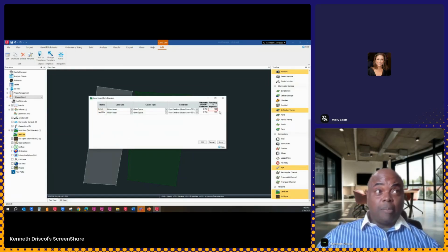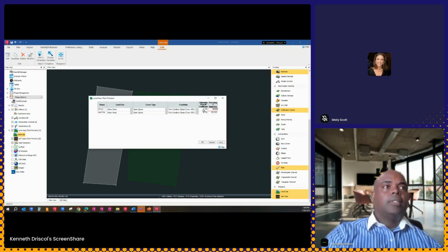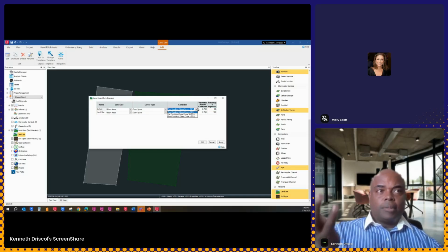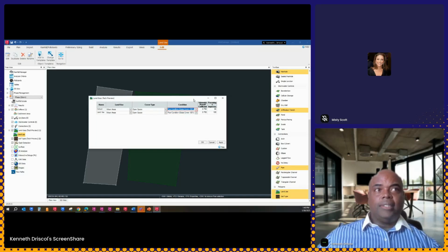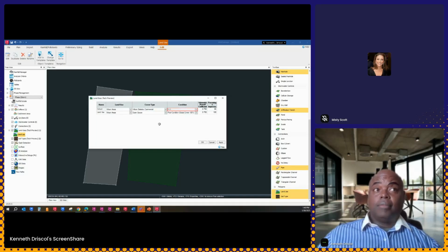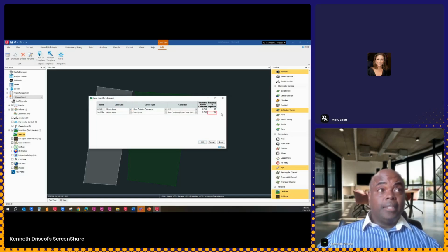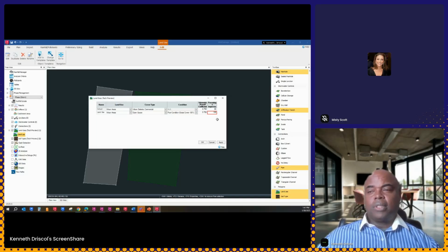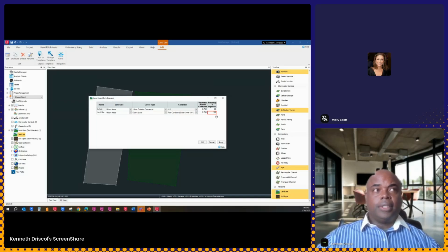With land use, you can put in a percentage, and you can also tell it specifically what condition, the cover type, and what land use. These are new with InfoDrainage. So again, percentage impervious. Well, we need to determine curve numbers if we're going to use multiple catchment areas, right? So land use.